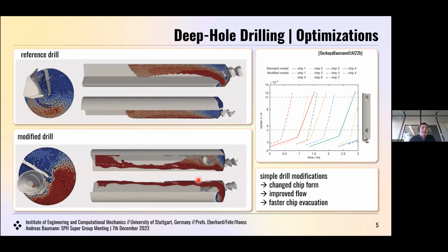So I already showed you the first approach to flexible modeling with SPH particles. We have seen some problems, like random oscillations. We have some high oscillations of the chip deformation, which we are actually not interested in. These high oscillations decrease the time stepping we can apply and thereby increase the simulation times. What we're more interested in is the general deformation of the chips.